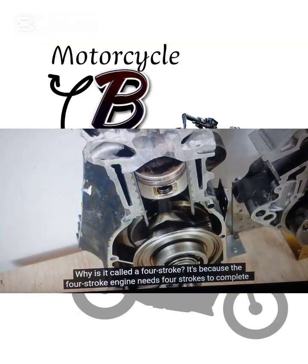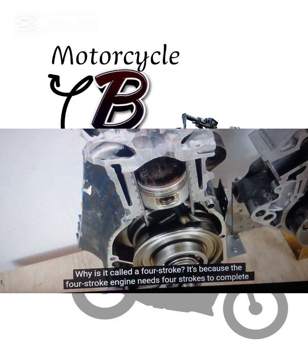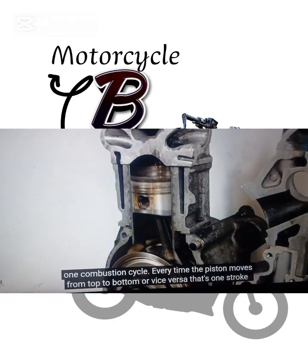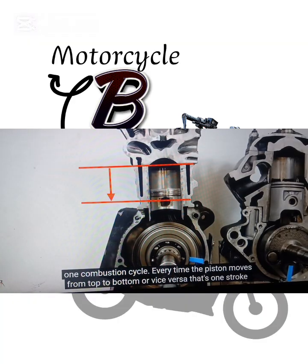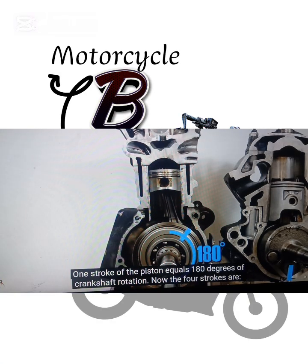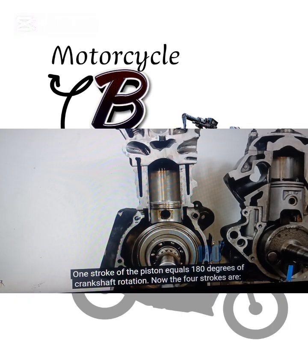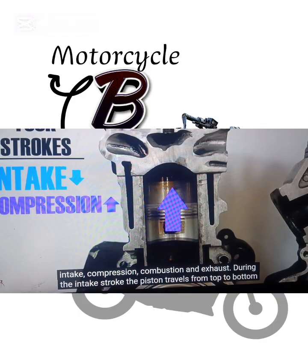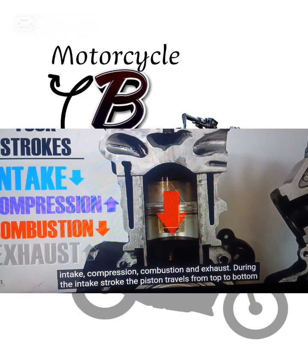Why is it called a four-stroke? It's because the four-stroke engine needs four strokes to complete one combustion cycle. Every time the piston moves from top to bottom, or vice versa, that's one stroke. One stroke of the piston equals 180 degrees of crankshaft rotation. Now the four strokes are intake, compression, combustion, and exhaust.